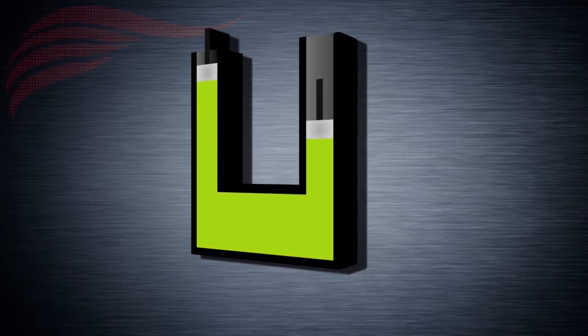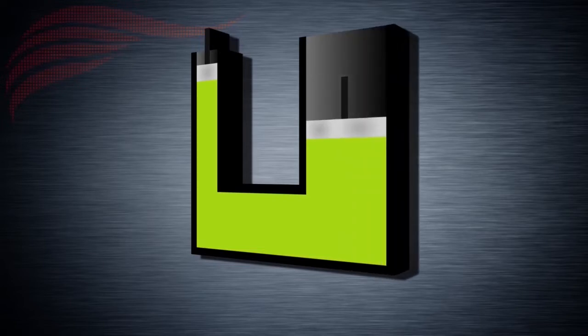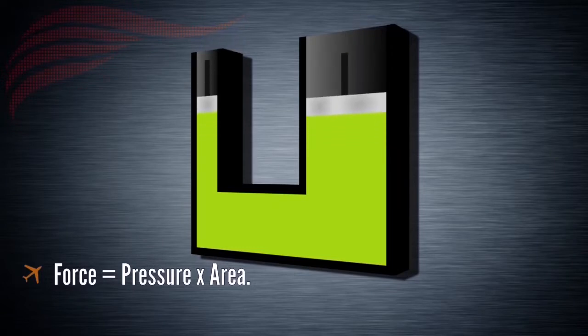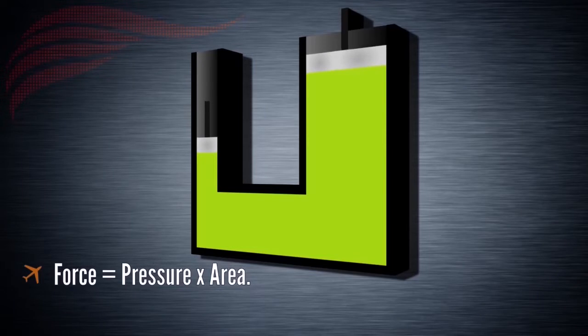This means that if we apply a 5 Newton force to the first piston, we'll get a 5 Newton force from the second. Let's take a look at what happens if we increase the size of the second piston. The surface area of each piston is crucial here. Let's give the first piston a 1 meter square surface area and the second piston a 5 meter square surface area. The equation we need to keep in mind is force equals pressure times area. This means that the pressure transmitted through the liquid varies as a function of the force that we apply to the first cylinder. So if we apply a 5 Newton force to the first cylinder, it will create a 5 Pascal pressure in the liquid.